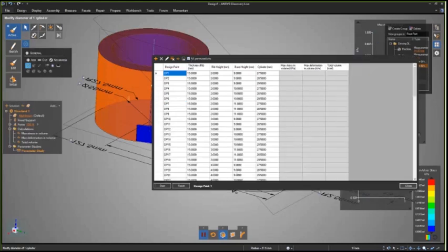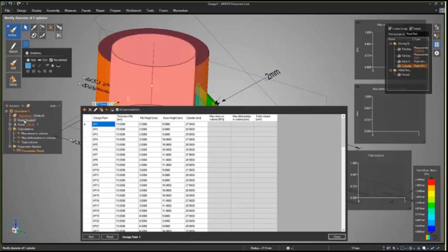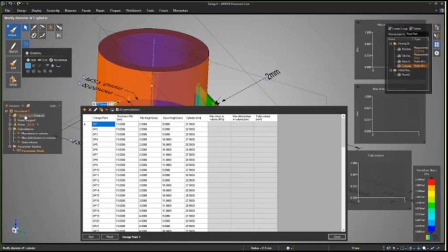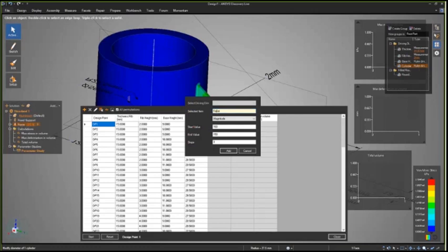What you'll notice is it's going to run through each one of those and calculate these values. Now, in addition to adding parameters that are geometric, you could also add parameters from the side here. The one that you cannot currently is material. That's something that'll be in the future. But if we wanted to see how this ran with a couple different forces, you can do that as well. I could add a parameter and select force from right here. If I want to see how a range of forces apply, I could do that, but we're going to cancel that there.